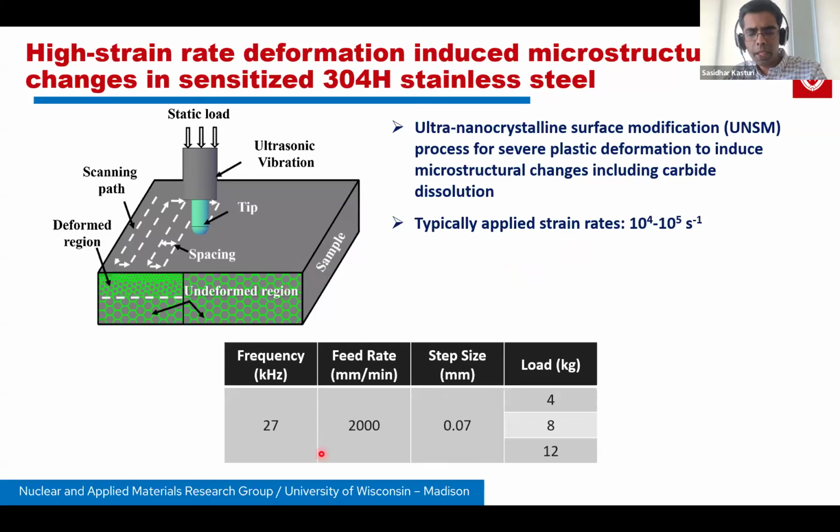So these are the typical process parameters. There's a frequency of the ultrasonic vibration of the loaded tip. That's of the order of kilohertz. And then there's a feed rate and a step size and the load that you apply that you can all engineer for a given application.